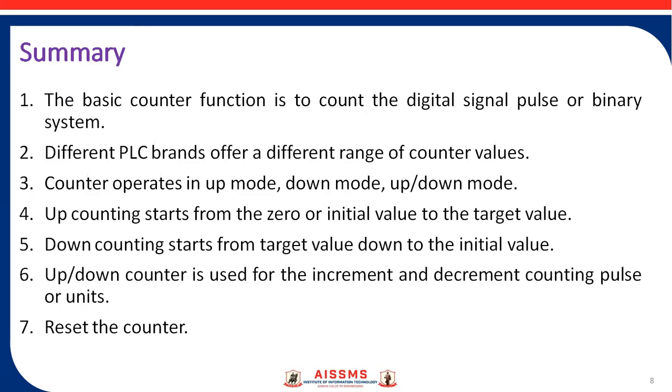Up counting starts from the 0 or initial value to the target value. Down counting starts from target value down to the initial value. An up-down counter is used for the increment and decrement counting pulse or units. Lastly, you can reset the counter.